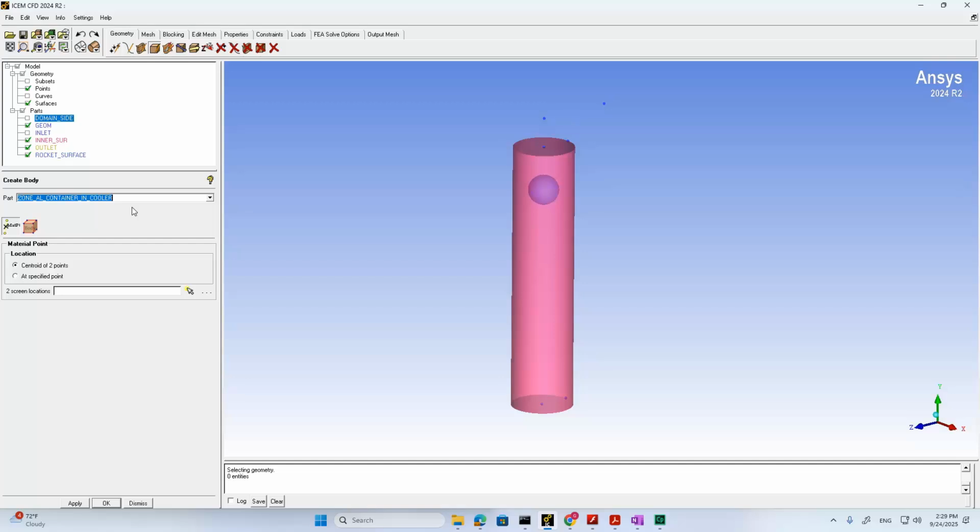So if you do not want an unstructured mesh in a certain space, you don't create a body in such a space. But if you want unstructured mesh in a certain sub-volume, you have to create a body, or more precisely, a body point in that volume.